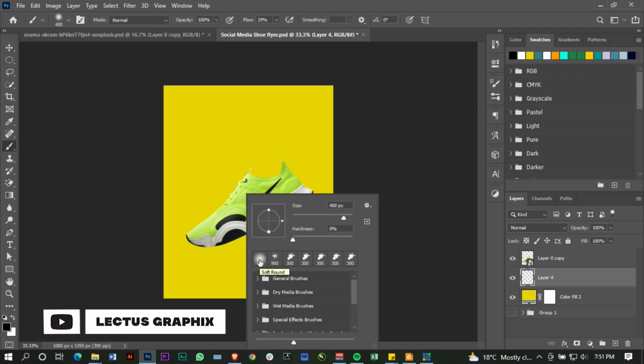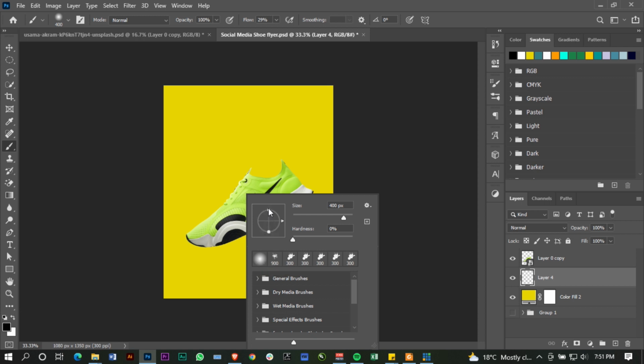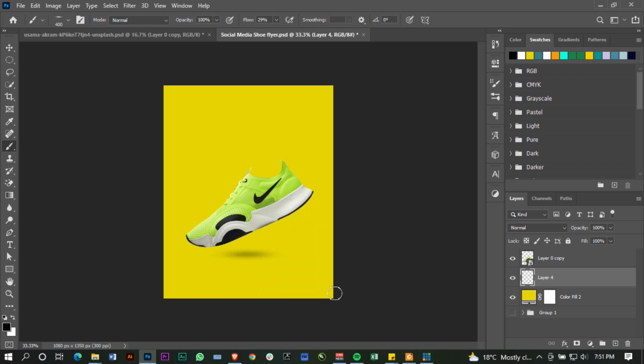Now what I want to do is to grab this from one of these points. If I grab it from here, I click, drag, and just turn it like that. As opposed to having this brush be straight like that, I want the brush to create the impression that it's on the floor. So that's why I'm turning this, so that when I paint here now, you see what happens, the shadow goes downwards.